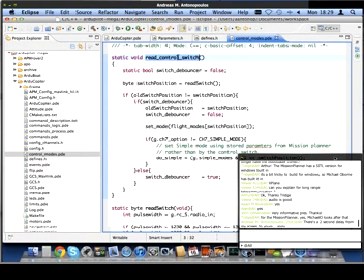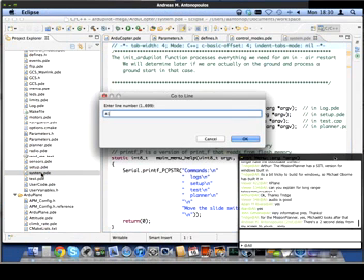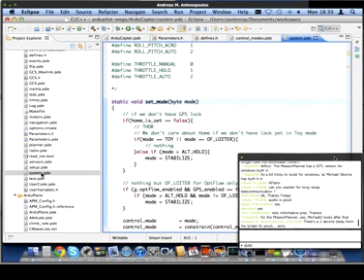You can see it right at the top there. It has the read switch call. If you look into that, you'll see that it has a hard-coded list of radio values, where it's decoding what's coming into the radio and then deciding which control mode it should switch into. The next important thing is this set mode call. What that's doing is taking the parameter, putting it together with the switch position, and then changing the actual flight mode that the copter's flying in.